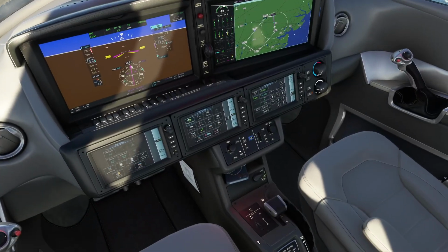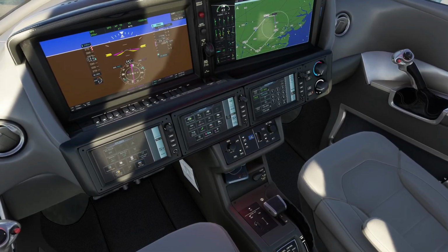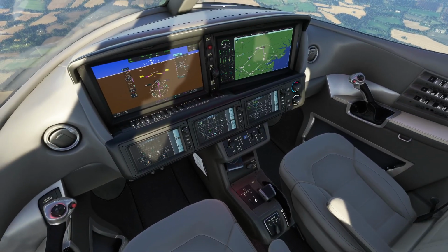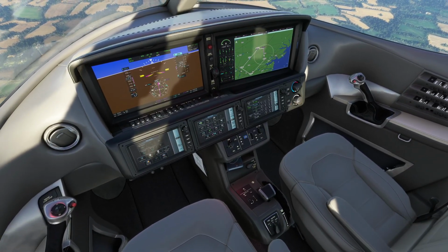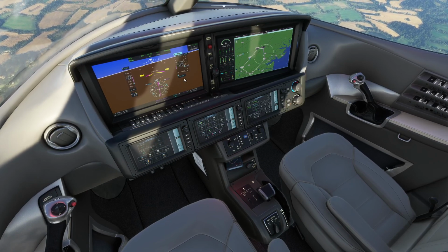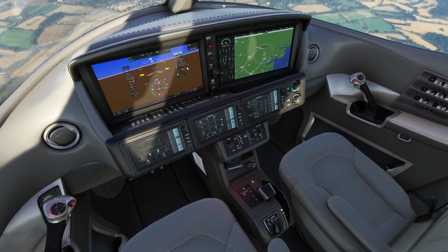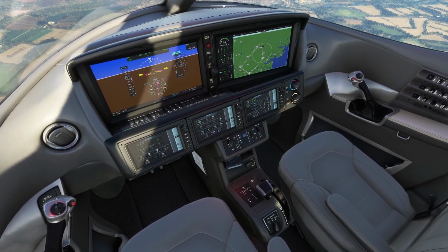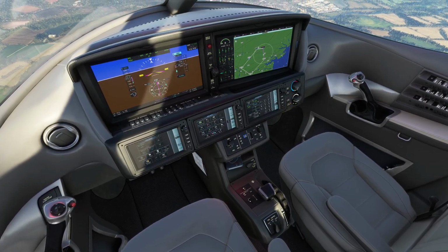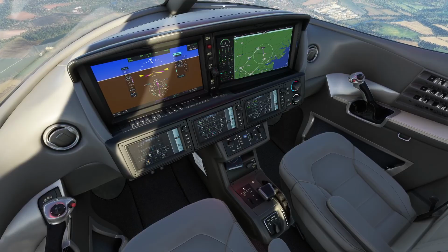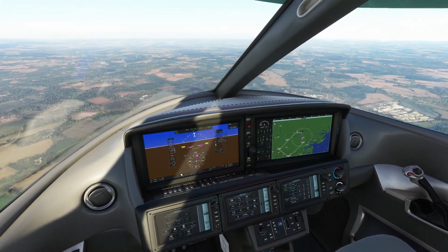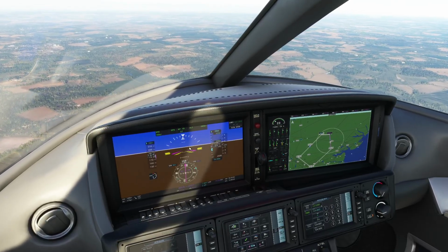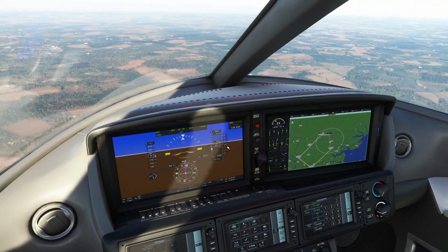So what you might want to do, I mean, we're quite a long way out still, but we might want to start pulling back that speed. And that might impact our descent. It will usually prefer to change your speed over your altitude. So it's not going to be descending potentially at the rate you've asked for if you've gone for a slower speed. So we'll go back for 180 knots, and we're just coming down to 2,800 feet.